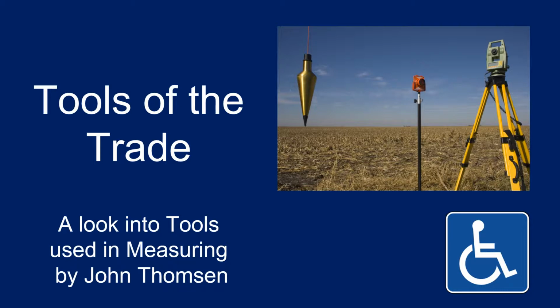In the middle, there's the target, which the transit basically literally points at and clicks. You're trying to align the target with the lens to get an idea of length. Generally, it does earth coordinates, and it's generally used for alignments in buildings as well as measuring property lines. The third tool you're going to notice on the extreme left is called a plumb bob, and it basically makes sure that the transit is plumb and perpendicular to the Earth's surface.